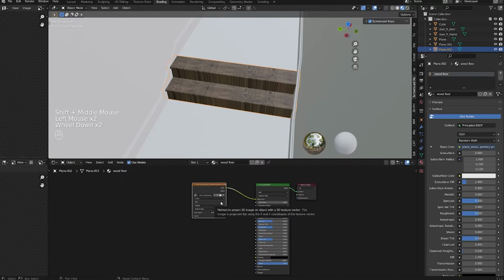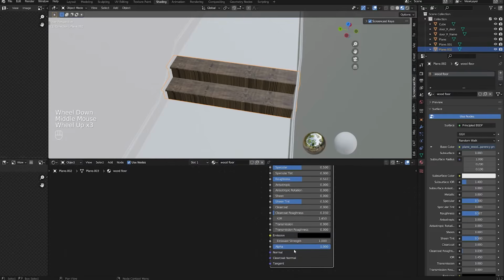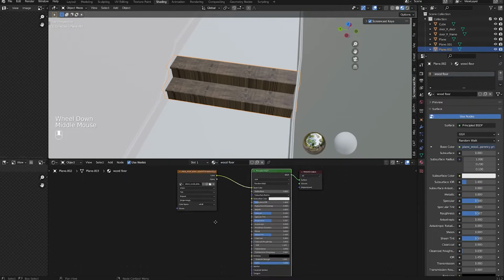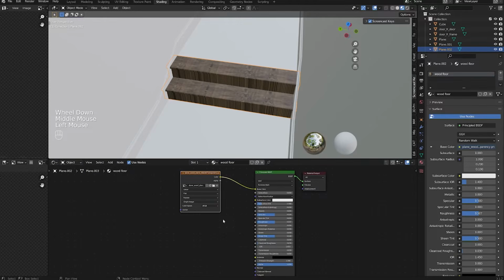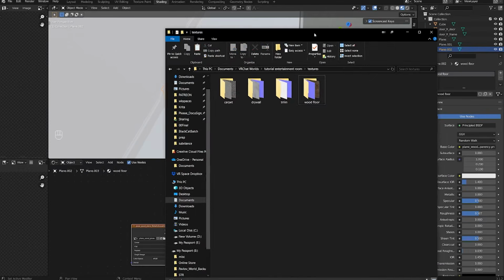We also need to get the roughness information from this texture and the normal information from this texture and get it onto our material. Because we have a roughness map and we have a normals map as textures, we need to pull those textures in. So the way we can do that is we can select this node, press Shift D to duplicate, bring it down, hit this little folder, and find a new texture. We're going to bring in the metallic smoothness. Now let's bring this over here.